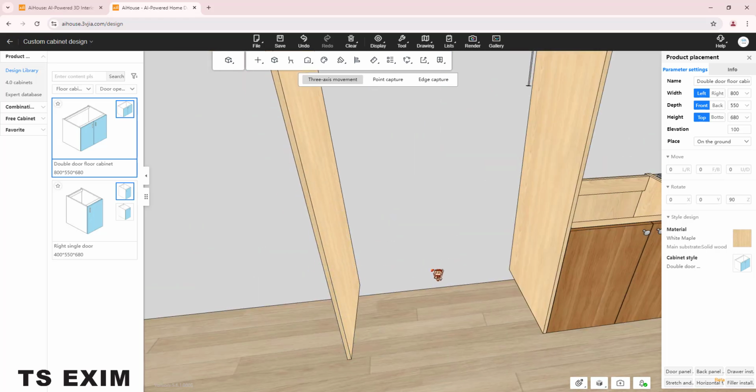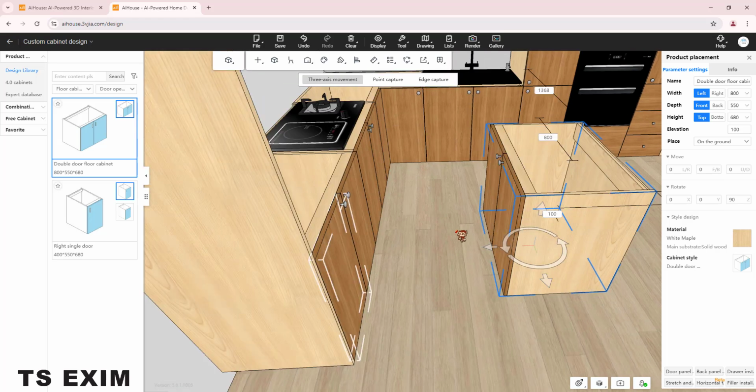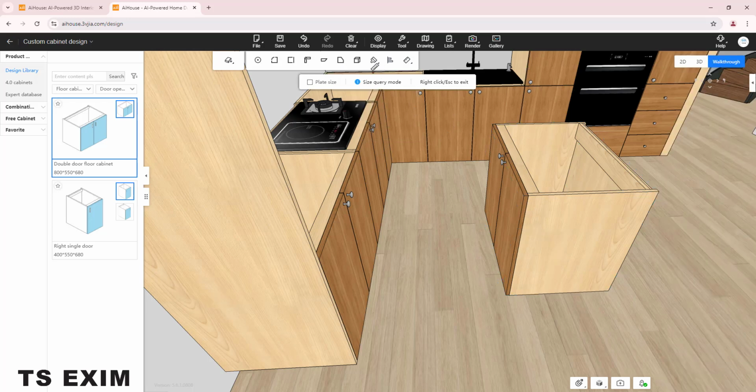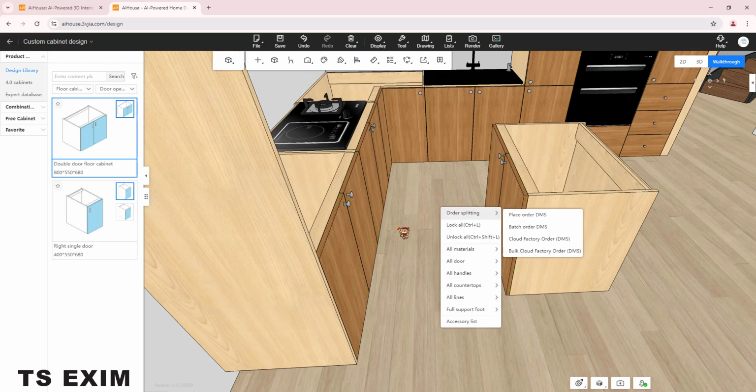Then, since the front side, you cannot see the distance, you can use this ruler. On top here got ruler icon. You can go to distance between two panels. Select this door and this door. Then you will see the sizing. This is the gap. So the gap is 690. You cannot adjust the number in here because this ruler will only show you the length. Cannot adjust. So you right click to exit, or you can press escape button.